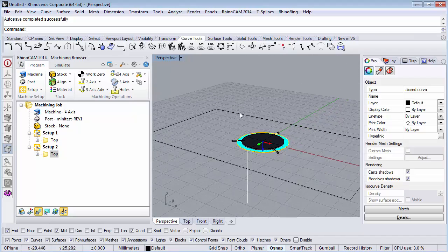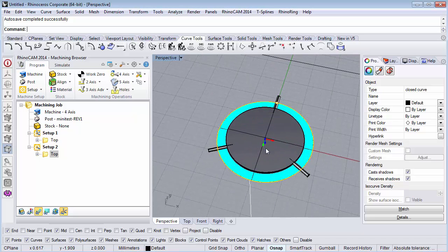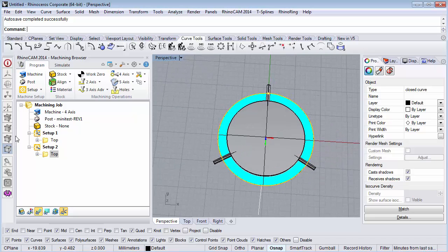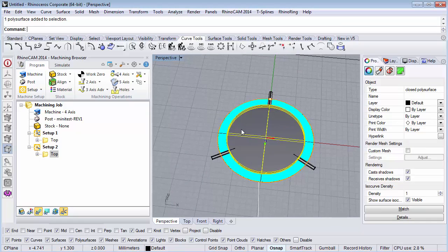Okay. Now the beauty of RhinoCam and the reason I used a big part like this is you could put this exact same information you have here. You could now not have to do all that work again. You can simply delete this block. I'm not going to actually physically delete it. You could delete this and you could put your pendant down inside the same circle, and then you could just draw the supports to it and go regenerate, regenerate, and then you could take that pendant out, you put the next pendant in, you go regenerate.